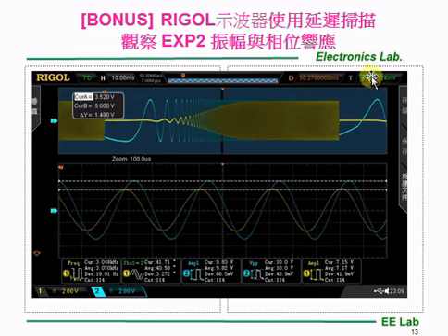Also connect the sync signal to the external trigger, with the trigger level set within the range of the sync signal. Also remember to use the average function to get better measurement results.